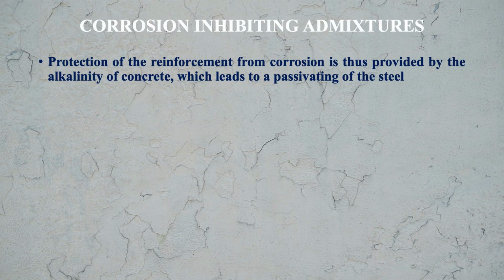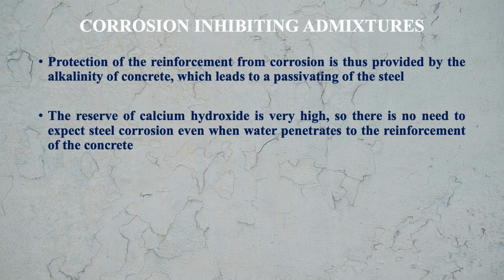Protection of reinforcement from corrosion is thus provided by the alkalinity of the concrete, which leads to a passivating of the steel. The reserves of calcium hydroxide are very high, so there is no need to expect steel corrosion even when water penetrates to the reinforcement of the concrete.